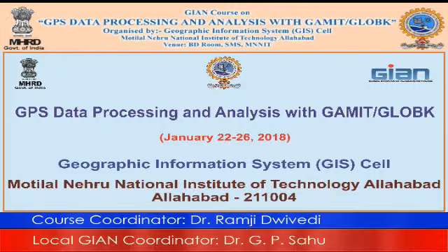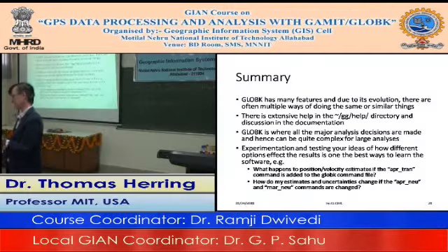The phase measurement we get from a GPS receiver is not a measurement of phase. It's the output of a state vector from a Kalman filter running inside that receiver. But back in 1990 when we did that, we tried to differentiate between the notional observations and parameters, which we call quasi. That's the reason for the quasi.